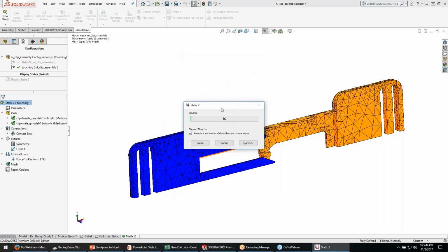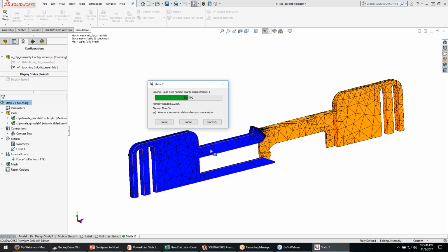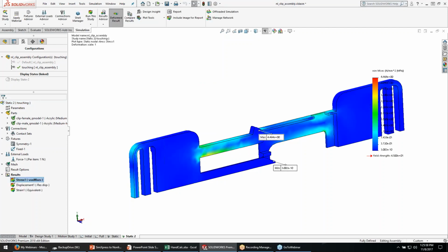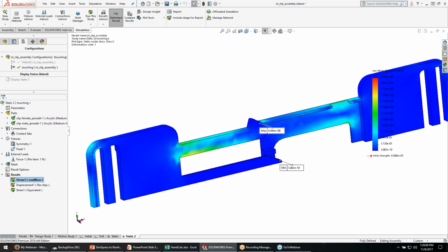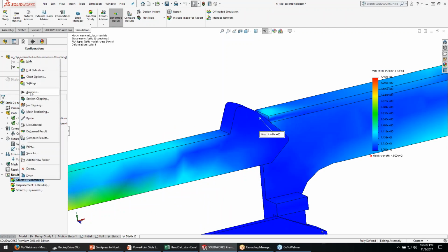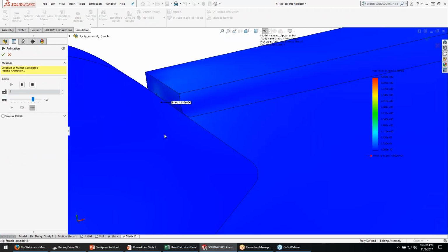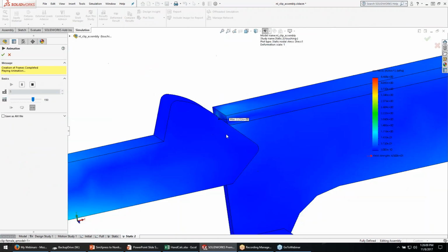I'm looking at the mesh here too. I'm thinking I should probably refine the mesh there so I have more than just one element through the thickness in this critical region. But I'll start it off this way. Hopefully it just runs pretty quick to give me a rough idea of the kind of behavior. But that is something I would consider changing, the mesh in this region. So it ran, and if I maybe animate the result, you can see a little bit of that sliding behavior there.